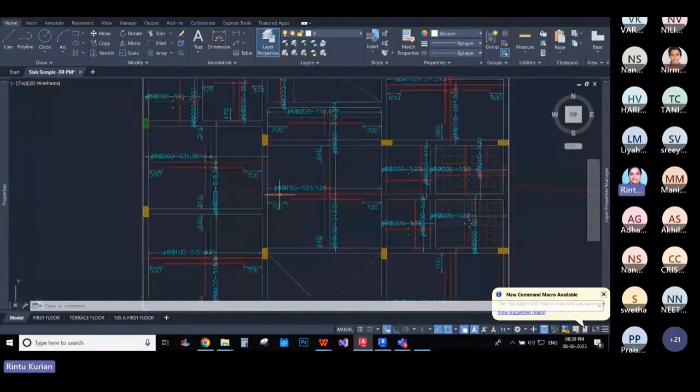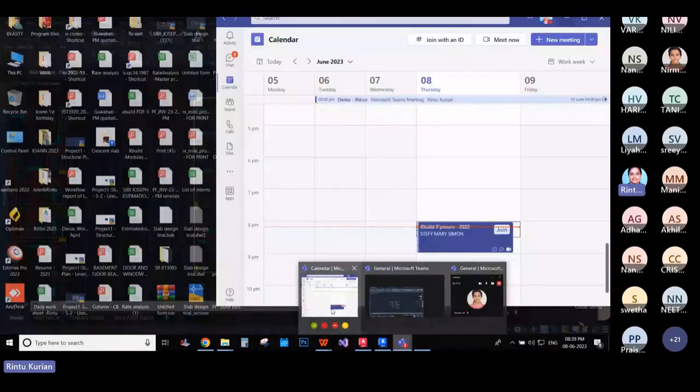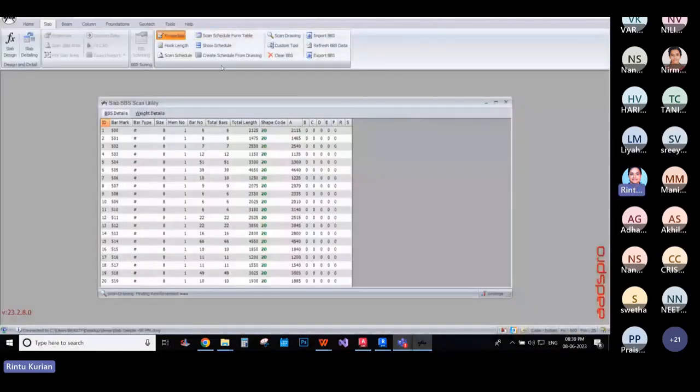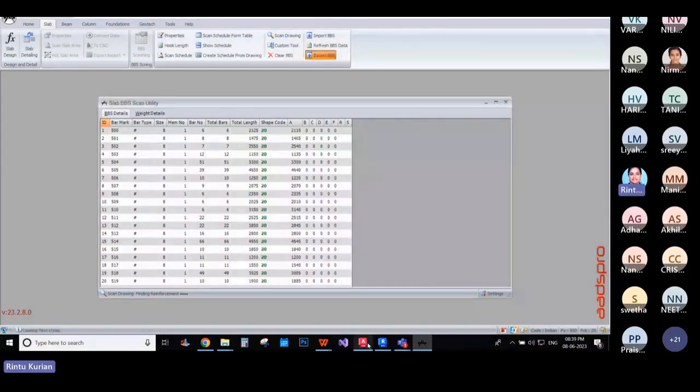And for the same, just come and check your property site. If it's export to AutoCAD, only then you can export to AutoCAD. Otherwise, you'll have to change the option. Then just click export. Come back to the AutoCAD file. Click on a clear space so that there is sufficient space for printing the table. The print will be automatic. Don't disturb the system. Just wait.